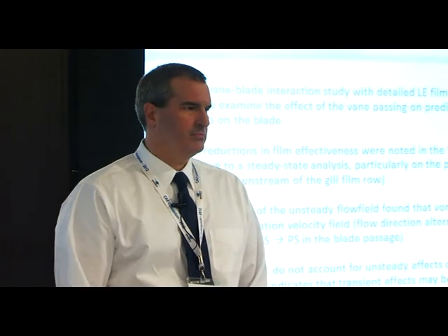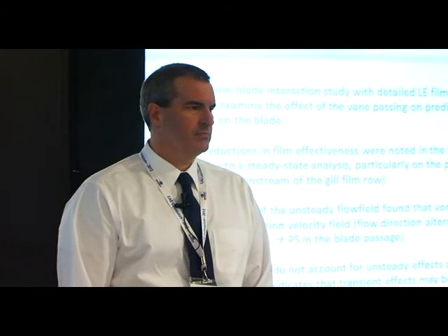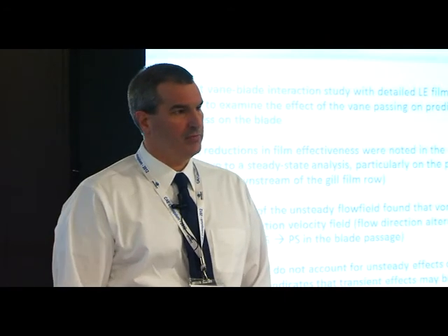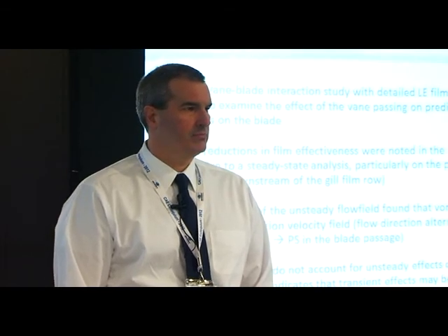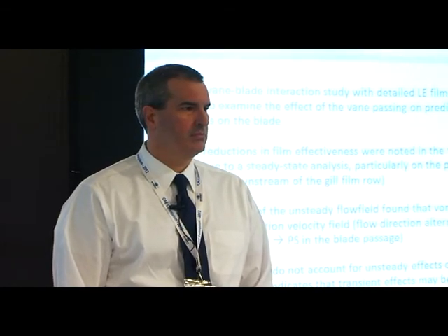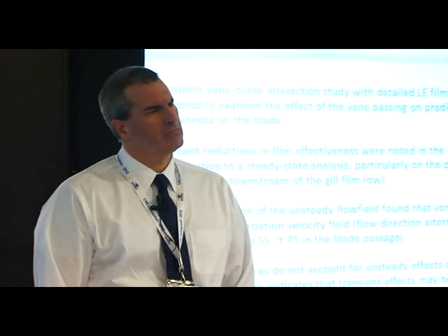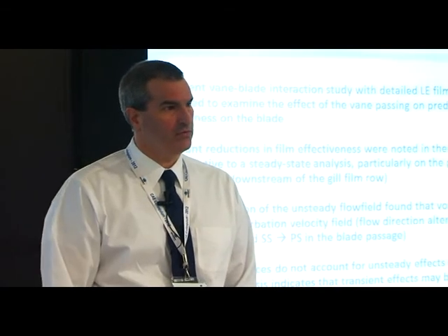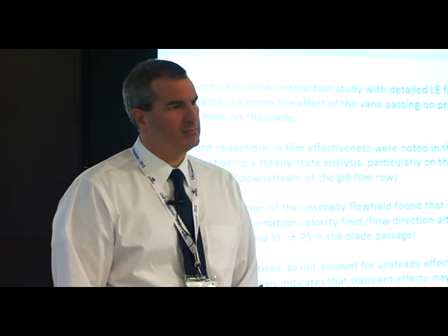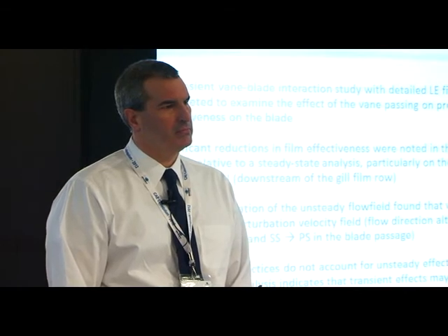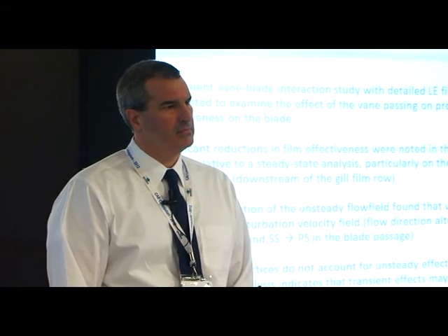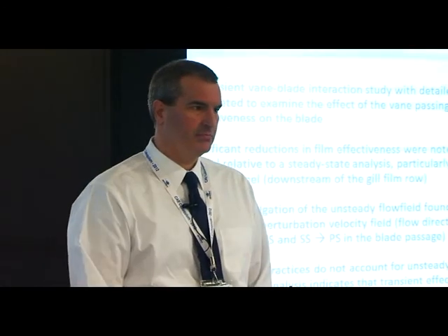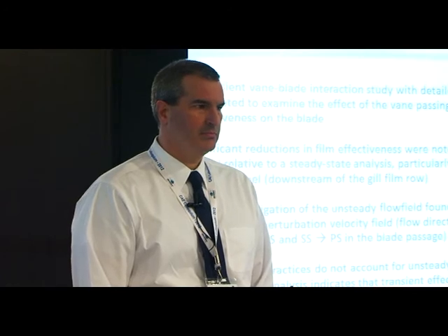In one slide I saw that you have done pseudo time stepping. That's only for the steady state. Pseudo time stepping is only for steady state. Right. So you mean to say that between the transients you are going for steady state in that time step? What does that mean? The pseudo time stepping is how CFX integrates the flow solver forward. Yeah, but suppose your time is about 3 milliseconds, over which you said, that was the test time. That means the CFD predictions should be of that time only.